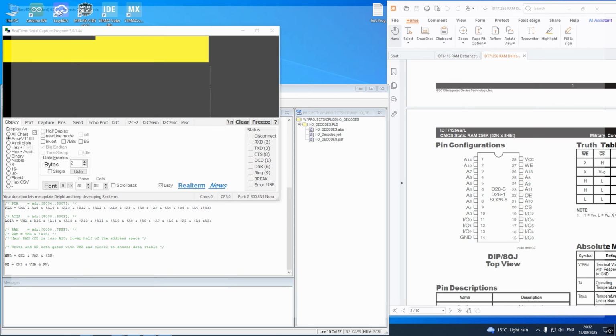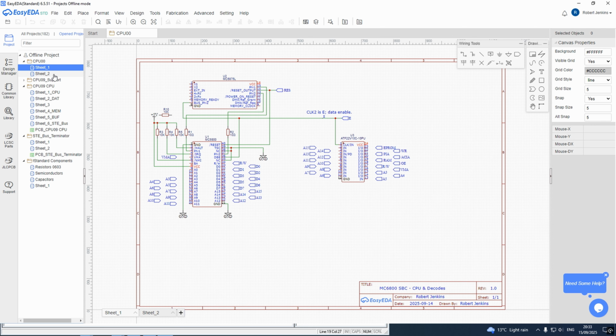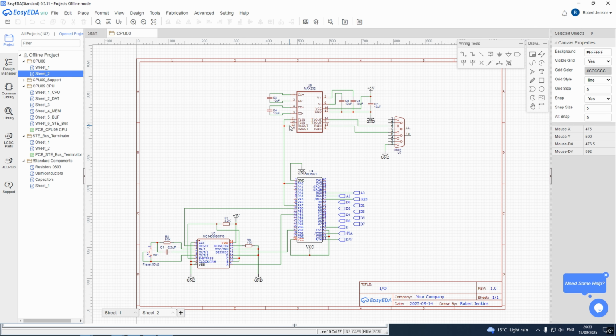I've also drawn out the circuit in the meantime, or partial, to try and get my own head around it and understand it again, because it's so long since I worked on it. Right, that's the wiring or connections as it was supposed to be, using separate 1488 and 1489 driver and receiver ICs that run off plus minus 12 volts.